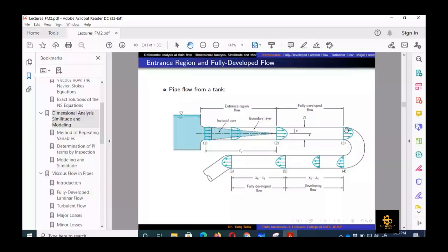this U-bend, and then after this U-bend there is again some developing flow at the start, and then a fully developed region after that. Then there is another discontinuity where the direction of flow is changed. So it means that this entrance region or developing flow occurs quite frequently in actual systems. Fully developed pipe flow is also there, but the frequency of switching between fully developed and developing flow is quite significant due to the use of different components in the piping system.